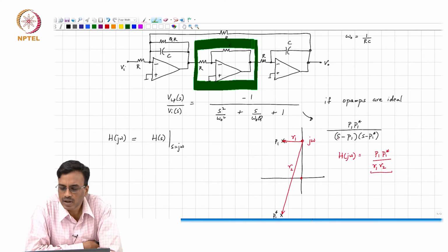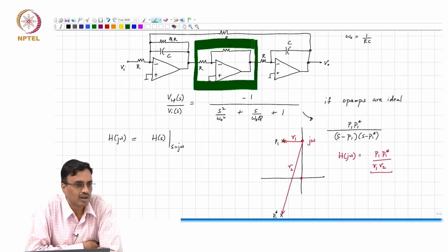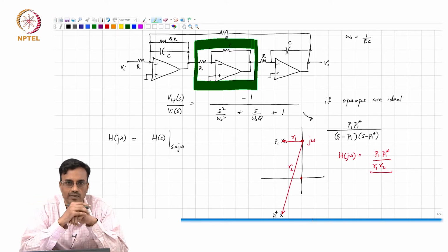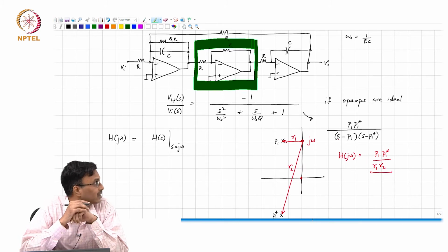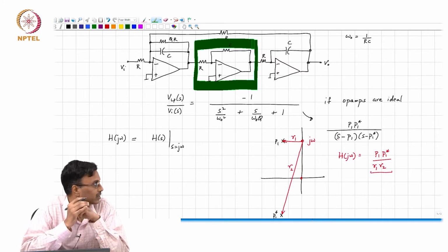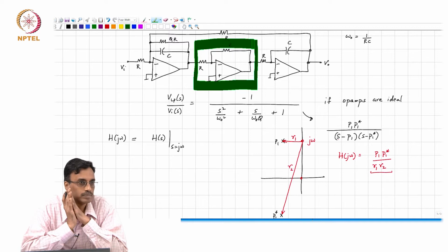Whenever you realize circuits in fully differential fashion, one of the advantages, apart from the fact that it is immune to common mode disturbances and a whole lot of nice stuff like that, is that inversion is obtained for free. It is simply obtained by interchanging the wires, right. So this assumption that the inverting amplifier is ideal, at least for the time being, is not a bad one.